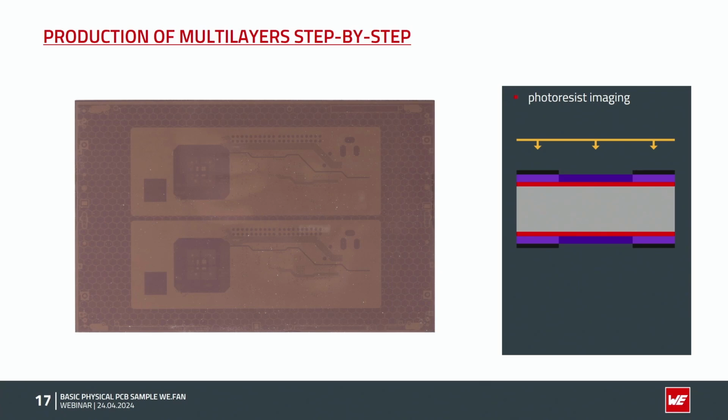So now we already can see the artwork. We also can see the overlay filling the area outside the artwork to achieve a well-balanced copper design for the whole panel. We also see registration fiducials and some small writings, legends, and so on.